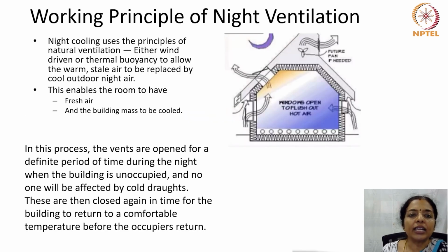Let us look at the working principle of night ventilation. Night cooling uses the principles of natural ventilation, either wind driven or thermal buoyancy, to allow the warm, stale air to be replaced by cool outdoor night air. This enables the room to have fresh air and the building mass is also cooled.